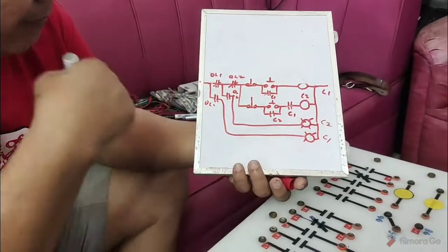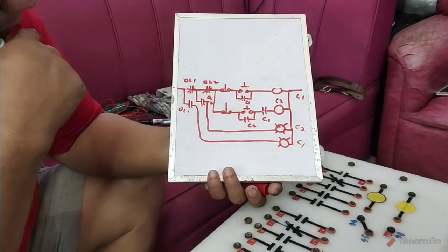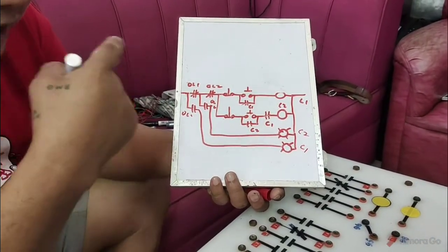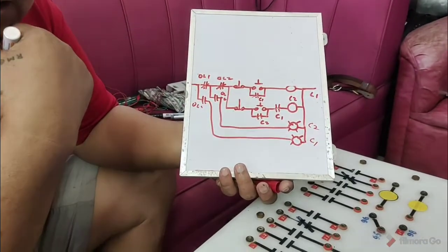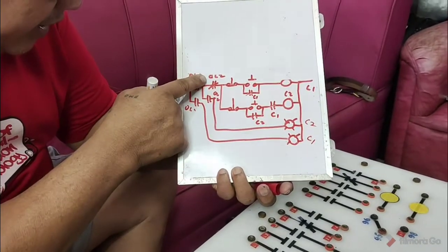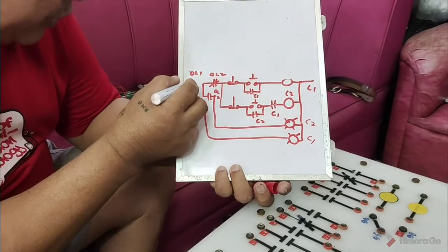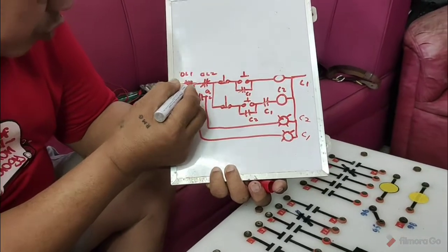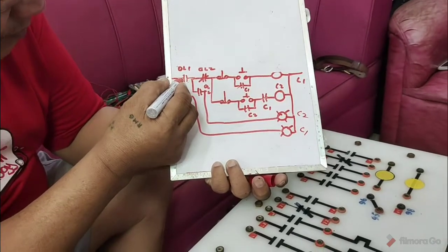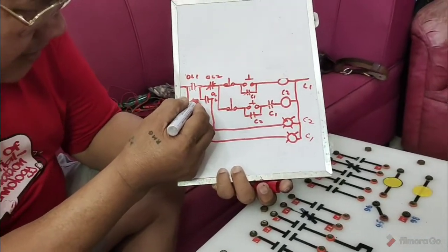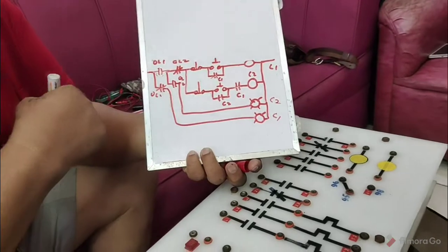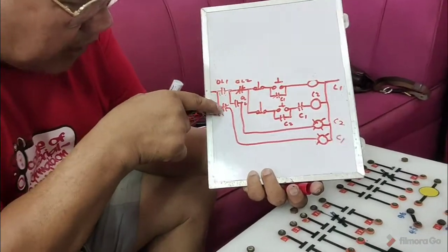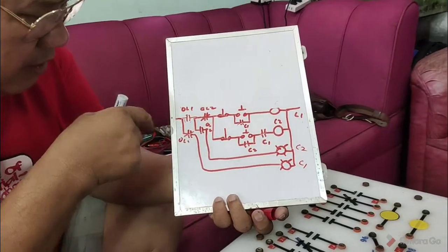It so happened that one of the motors is overloaded, either number 1 or number 2. So let us see, number 2 is de-energized, overloaded. So the normally closed becomes open, and the normally open becomes closed, because the contact here will transfer to normally open.